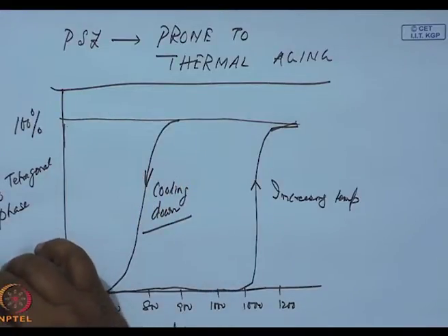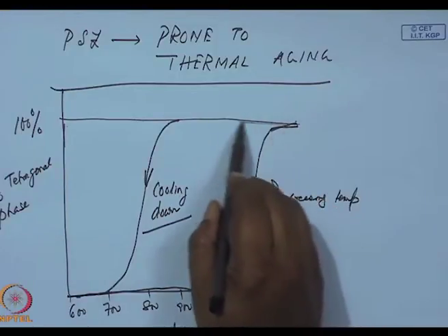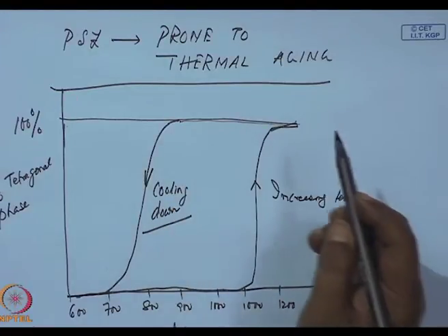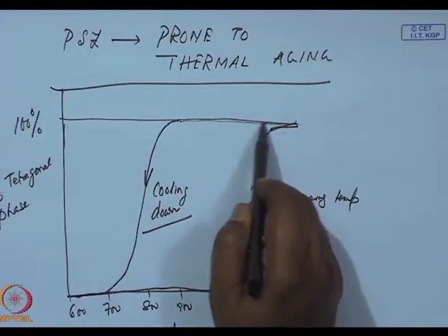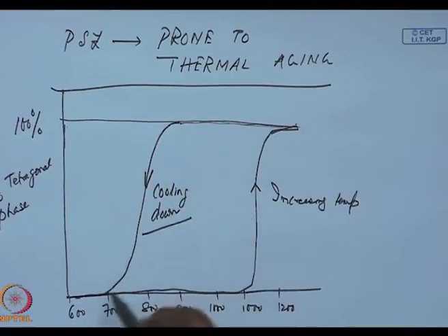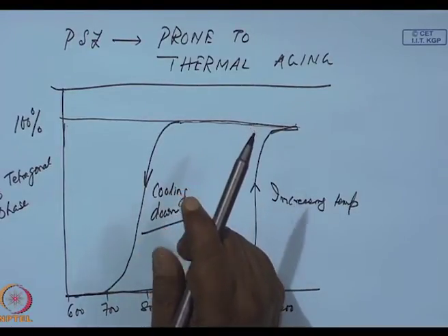I am cooling it. During this period the tetragonal phase is retained, and as I am cooling down, only after here the monoclinic phase comes up.